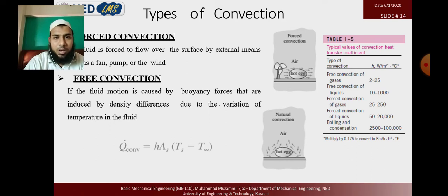But if the ice layer forms on the cooling plate, it resists the absorption of heat from the compartment itself. It gives some cooling throughout the surroundings, but the absorbent capacity becomes lower. So the upcoming fridges are coming with forced convection, with a fan installed inside the fridge, which you cannot see because it is hidden in the compartment. And you also cannot see the cooling plate because it is inside the compartment. So there will be forced convection flow.